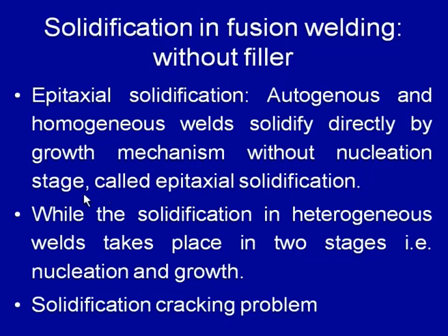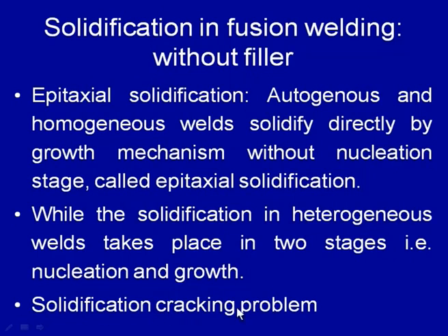If we see those situations where the filler material is not used, but the base material itself has a very wide solidification temperature range, those autogenous or homogeneous welds are found to be sensitive to solidification cracking, because a lot of residual stresses are set in along the weld center line, and that increases the cracking tendency along the weld center line and results in solidification cracking.